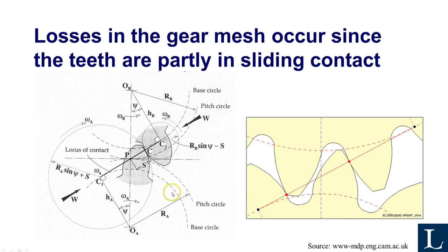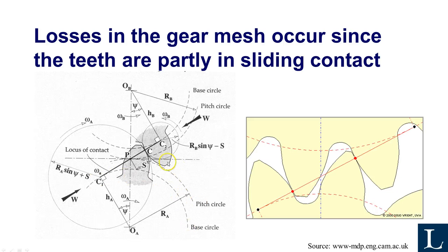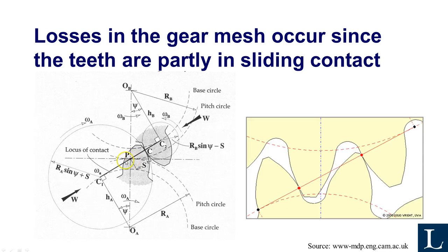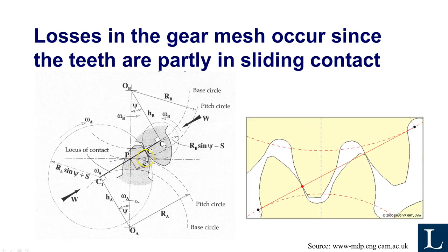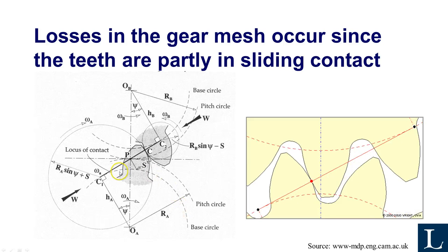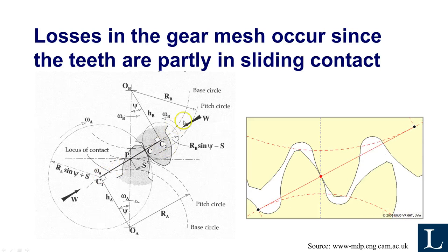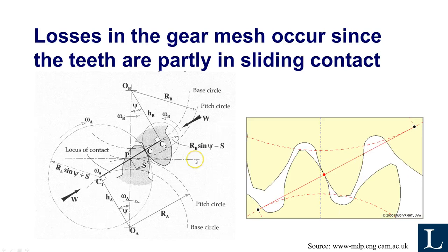You remember also gear geometries that you have the base circle, you have the pitch circle. Pitch circle is the corresponding radius of the two wheels rolling in contact with each other. Base circle is the circle from which the line of action is unwound from the one wheel to the other one. Coming back to that very soon.